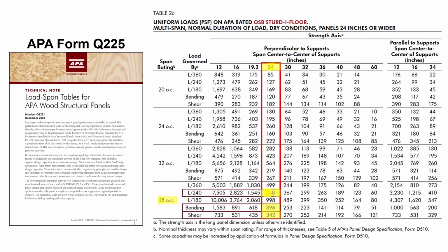Effects of support width have also been considered when determining the loads based on shear and deflection. Supports are assumed to be 2-inch nominal members for spans less than 48 inches and 4x members for 48-inch or greater panel spans. One final note about these tables is that they assume normal load durations. For these reasons, the values highlighted differ from those we calculated in our first example. However, if our design conditions match those assumed for these tables, they provide a quick reference point.